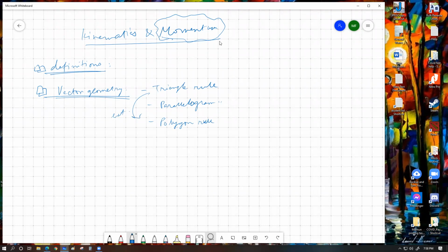One of the primary things that we need to understand for the triangle rule is this: if we have a vector equation that looks like this, let's say vector x plus vector y equals vector z, the way the triangle rule works is that we should, with scale and direction, draw the vectors x and y one after another, in the way that the figure has them, and then the completing side of the triangle would give us the resultant.